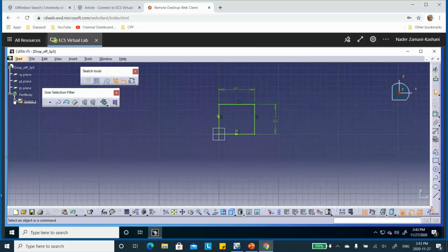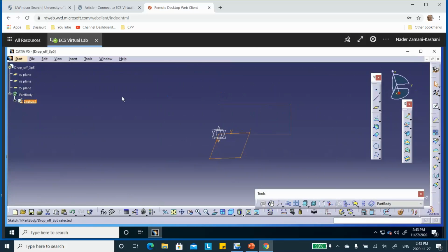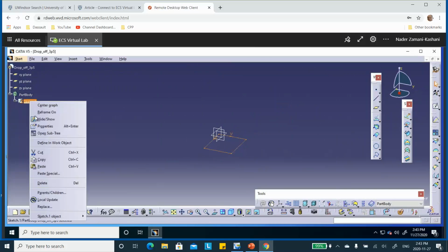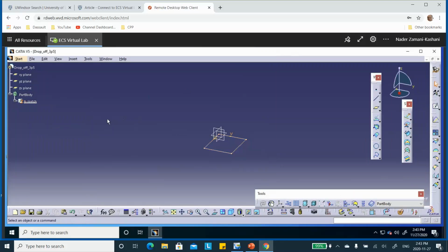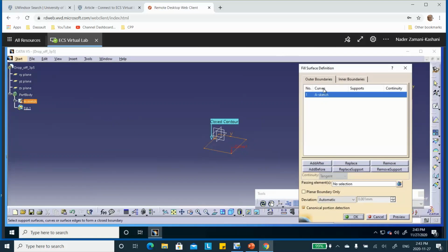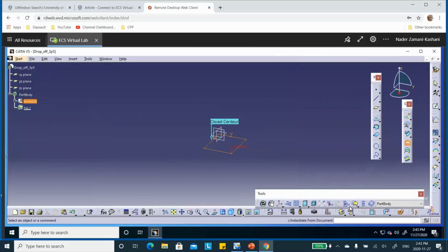So if it helps you, you can name these things. We exit that sketch, I will rename it, properties, I will call it sketch for A. Trying to get organized. Okay, good. Now fill it. Where is the fill? F-I-L-L, right there. Fill. And very good. And join.